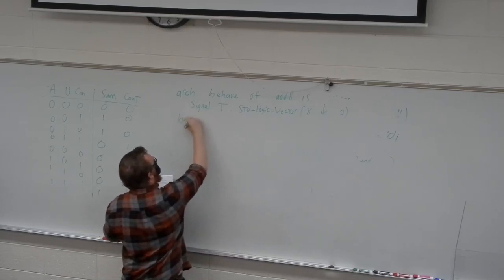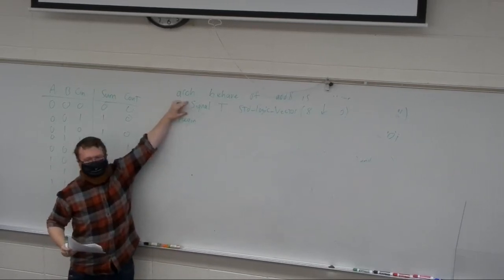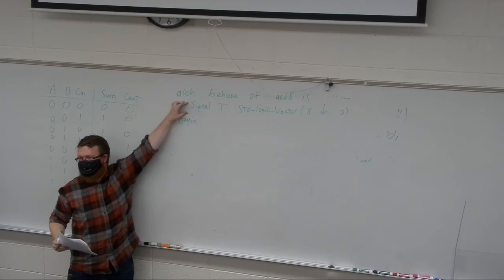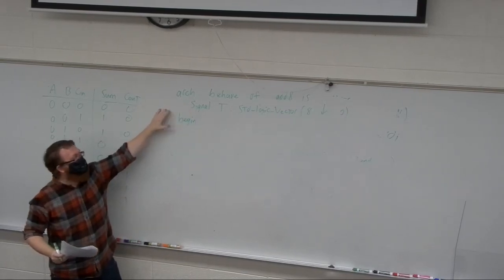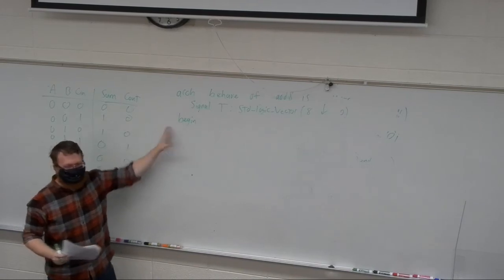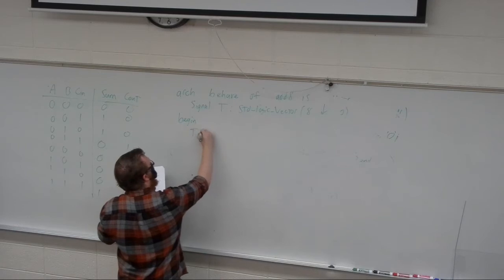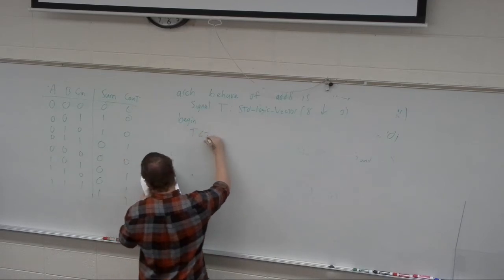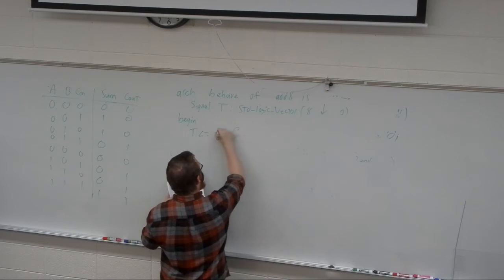Then I say begin. Architecture: declare any signals and components that you might need, and then you say begin. Declarations, then behavioral. Then it's just a matter of saying this signal T is going to be, well, let me write it and then I'll cover it rather than talking.